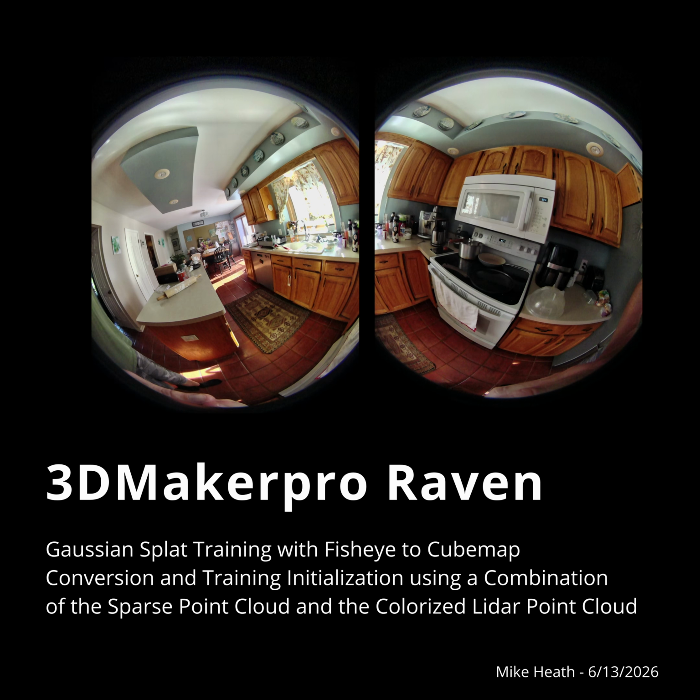In this video, I'm going to show a little bit about some experimental processing of data from the Raven. This is an interior scan of part of a house, and what I did was include processing that did a Fisheye-to-Cubemap conversion after aligning the fisheye images, and took that sparse point cloud and combined it with a colorized Lidar point cloud as the initial PLY file for training with LichtFeld Studio.